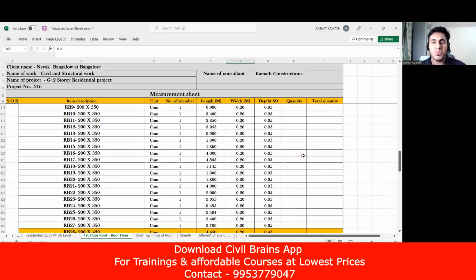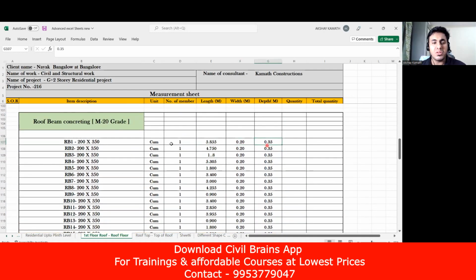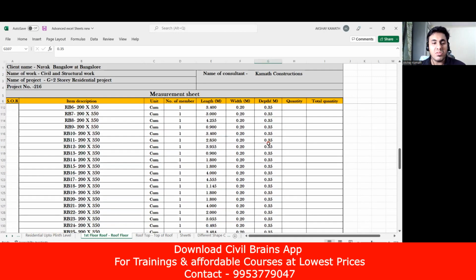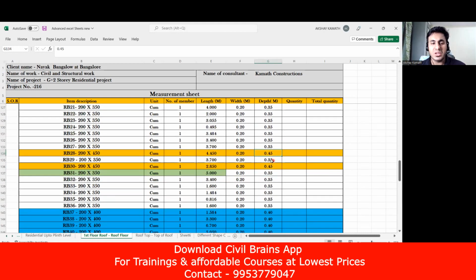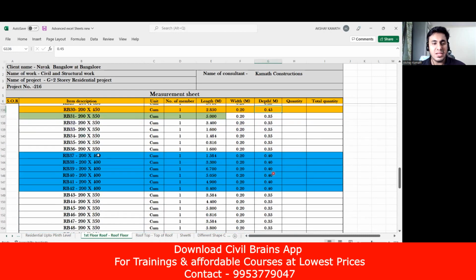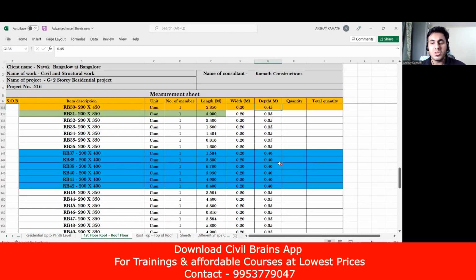So what will happen? In the depth part, you just input 0.35 first and drag everywhere. Okay. After that, since I've given a color, now it is easy. So this is 450, I'll input 0.45 here. 350, 0.35, 450, 0.45, 350, 0.35, then 400, so 0.4, 0.4, 0.4, 0.4, and 0.4.